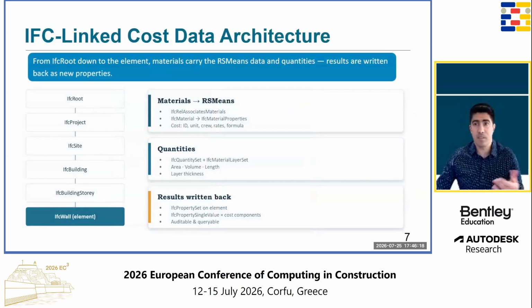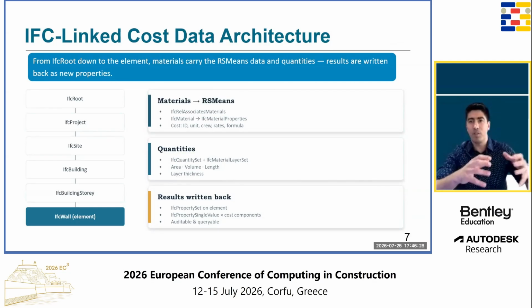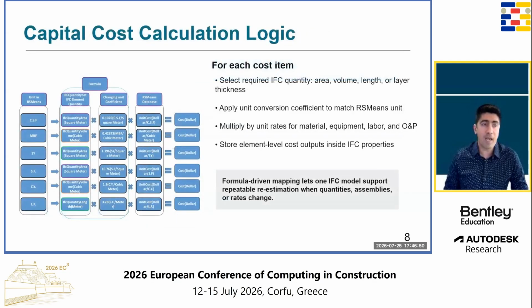This is a core technical slide that shows how the prototype goes through the IFC objects and uses the materials as the bridge between geometry and the cost data. And as I mentioned, it all happened in IfcOpenShell as the implementation mechanism for reading, writing, property sets, and also quantity access.